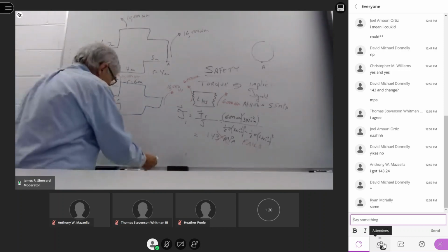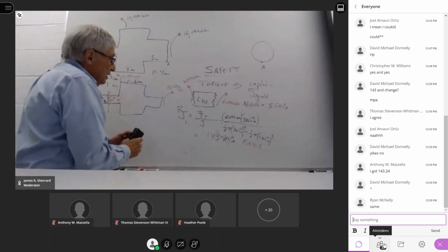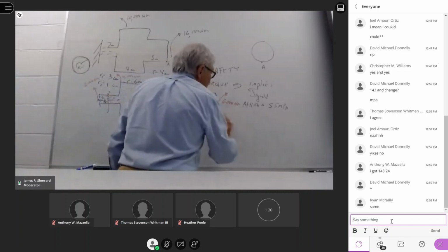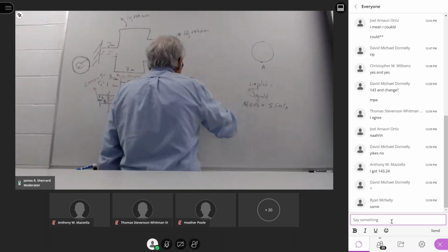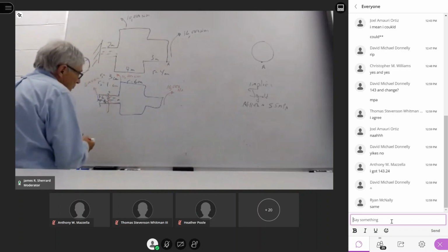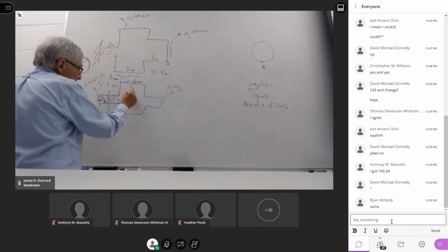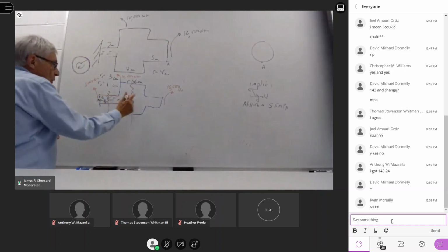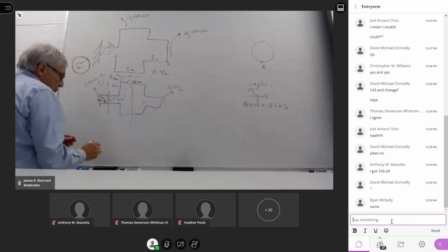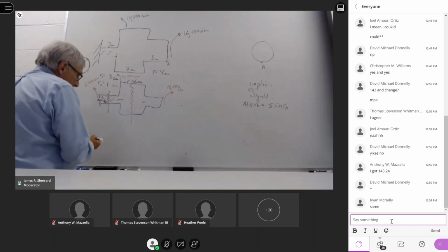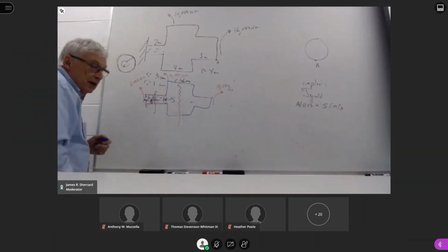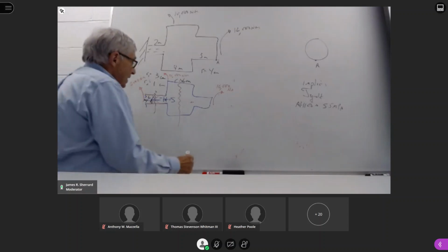Okay. We now need to look at the middle section. So I need to go back and do a complete free body diagram for that. In this case, I'm going to cut this in the middle region because I want to see what is going on anywhere just to the right of there, just to the left of there. So I'm in section 2. When I do that, I'm going to look at this section as the left-hand side. I'm going to do a free body diagram of just that.